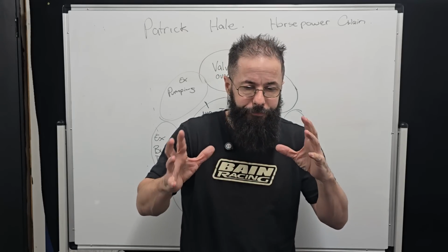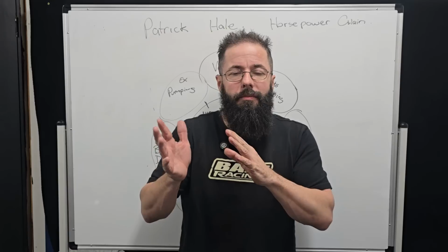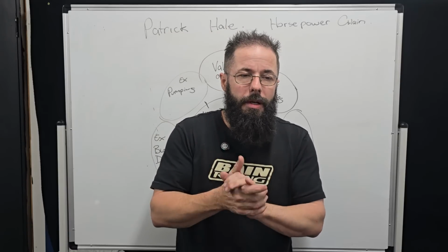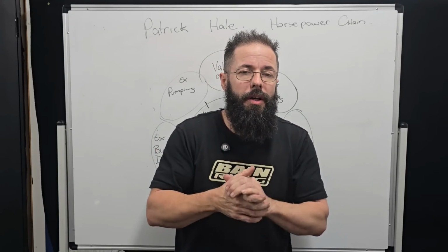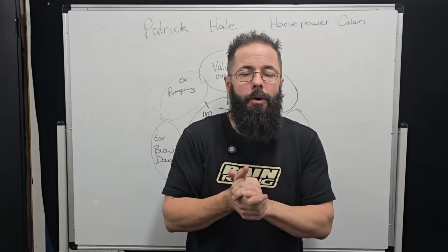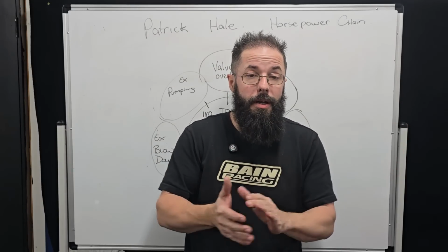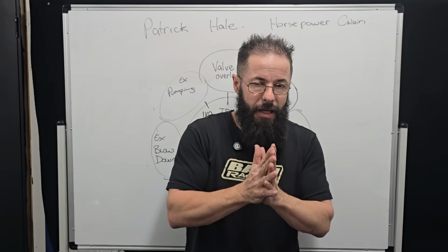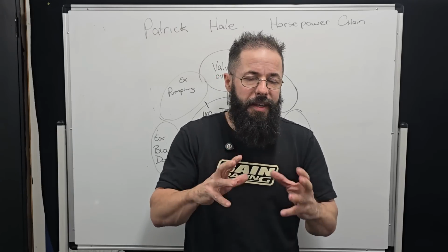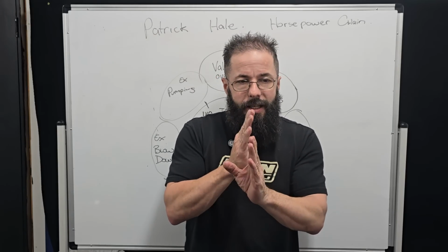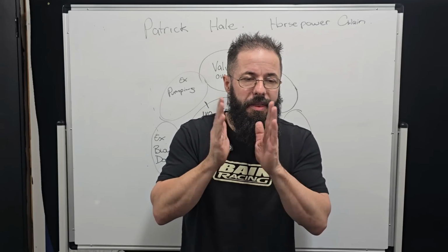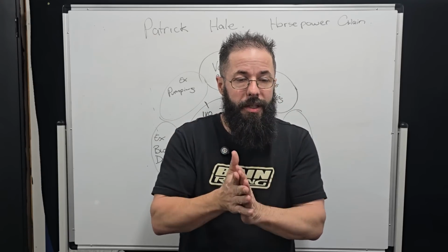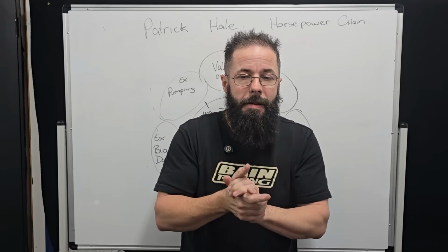So with variable valve timing and variable everything, LSA, duration and lift and everything they've got now, we can have far broader horsepower curves and far broader torque curves, which makes it easy. But yeah, if you have fixed camshafts, that LSA is going to work really, really well at a specific area, maybe a 1,000, 1,500 RPM window. And that's what you need to tune to.